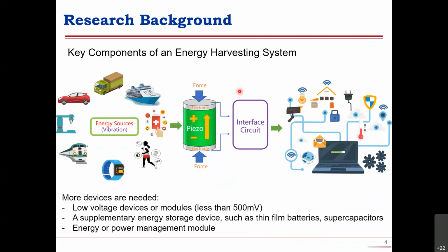And then we use the interface circuit. Why do we use the interface circuit? Because the electrical property of piezoelectrics is very different. They have a very large resistance in parallel with a capacitor.